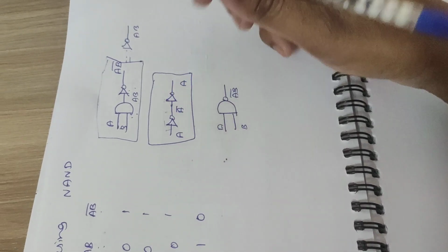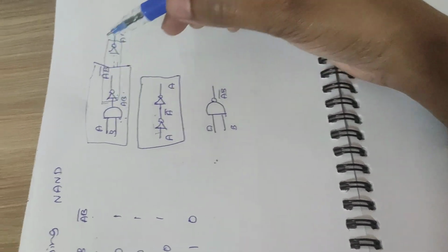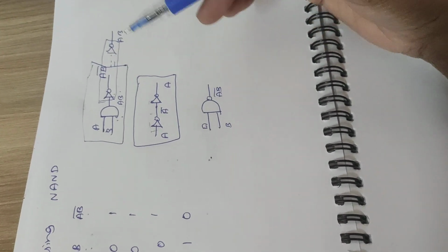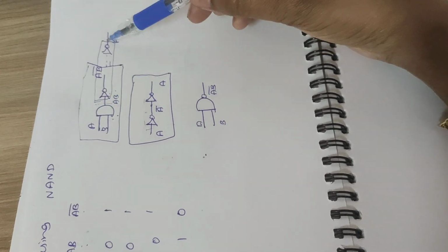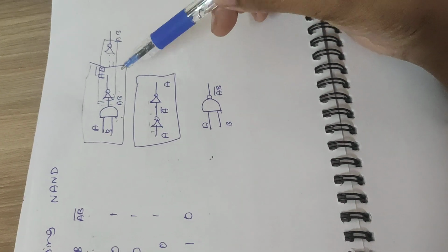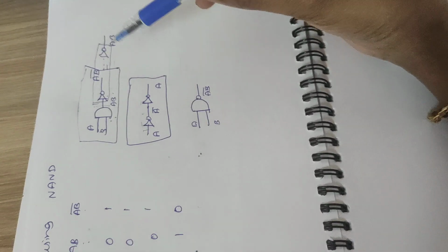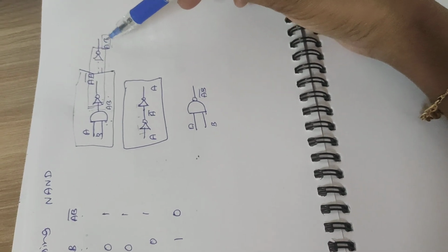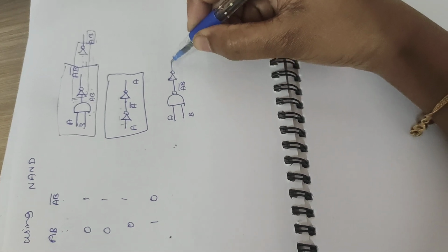So if I have another inverter here, both will logically compensate the inversion property. So the output we will be having here will be what we had before. These back-to-back inverters logically don't play any role here; it is the buffer role it's playing. So we will be getting AB. So here we can just add an inverter to get our AB.